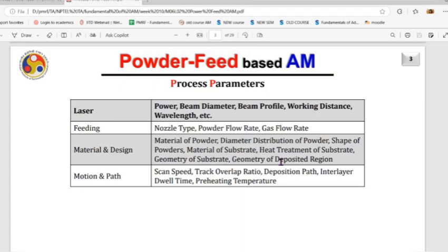So that is the one laser that you are using for one system. It has a direct relationship with the absorptivity of the metal for that laser. Like aluminium absorbs IR laser less than what stainless steel absorbs. So that is also playing a very important role. But when you change the laser, for example, blue laser, it has 445 nanometer wavelength. That means its absorptivity is way higher in the case of any other metal. So your whole process parameter set will be changed.